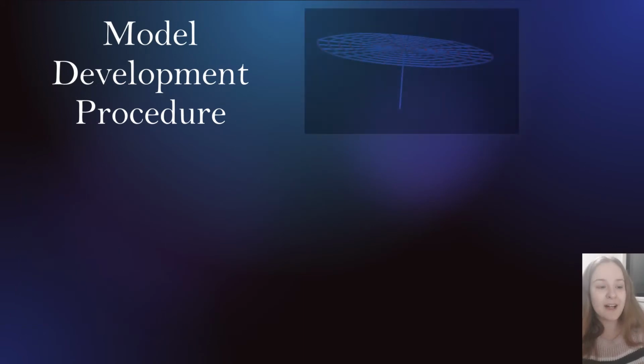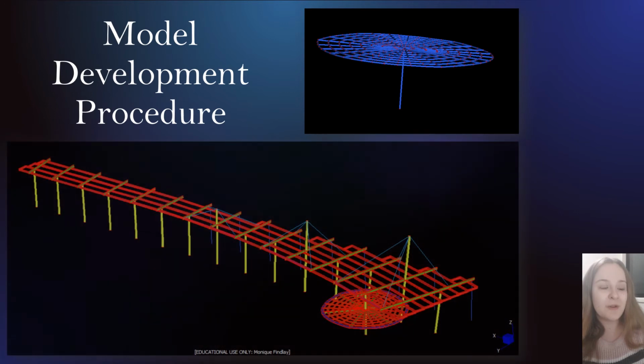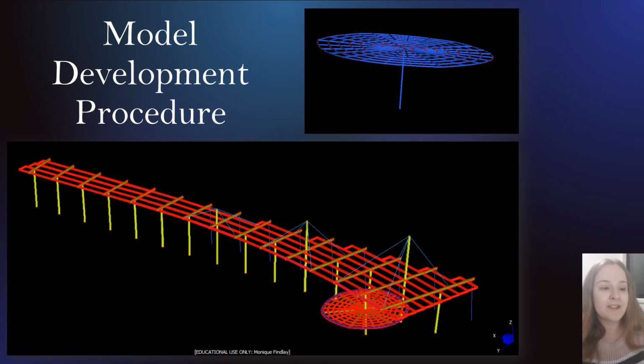The cafe frame was later added to the walkway structure using the same method to measure node coordinates. The parabola tool in Strand 7 was used to create a parabolic curve with 16 splits between selected coordinate points, producing the circular shape of the cafe roof. The completed design contained 588 nodes and 738 beams. Linear static analysis was performed for each of the load cases developed.